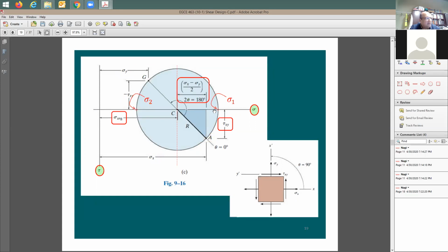So in some cases, both of them are going to be tension. In other cases, this one's going to be tension and the other one's going to be compression. This one will come up in concrete design and concrete analysis. If you're doing other analysis, you may have both of them in compression, provided that you have compression like in a case of hydrostatic pressure, or compression pressure coming from all sides when you start the analysis. So this one here is going to be called sigma 1 again, and this one's going to be called sigma 2, which means the two principal stresses.